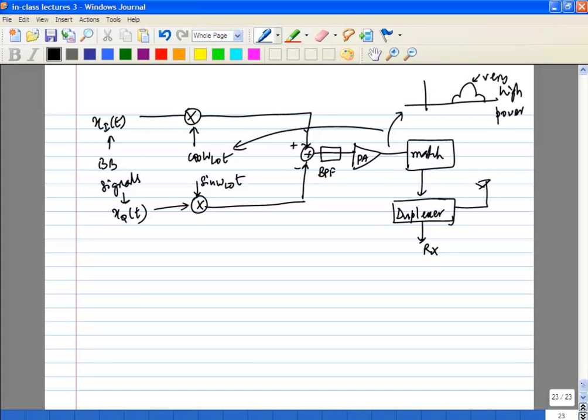When you are trying to transmit so much power, the PA spectrum, either through electromagnetic coupling, or through the supply if they share a common supply, or through the substrate if they are on the same chip, you could see what is called PA pulling. This modulated spectrum will corrupt your pure sinusoid and give you a very noisy system, a noisy LO.